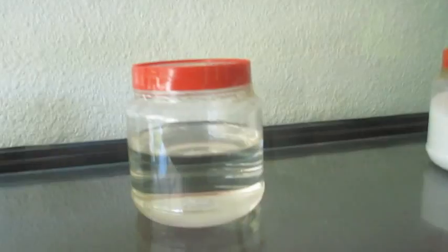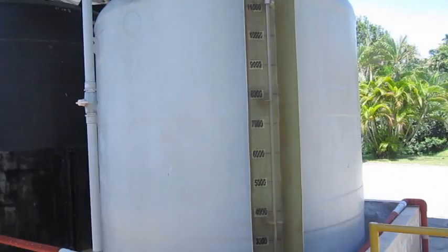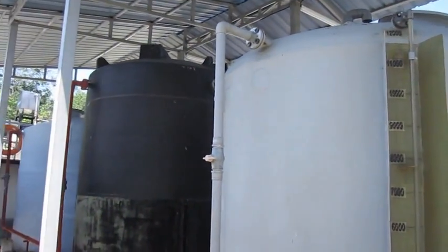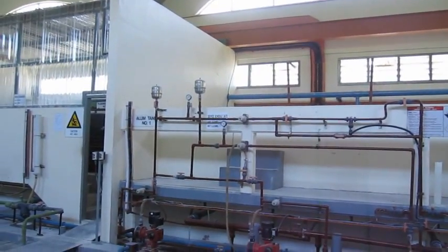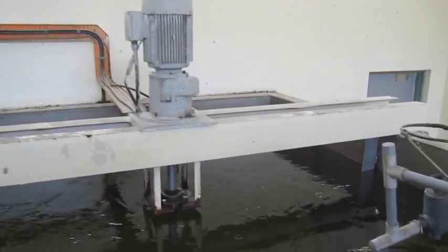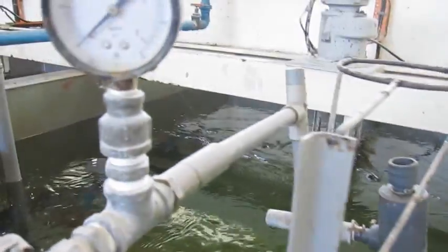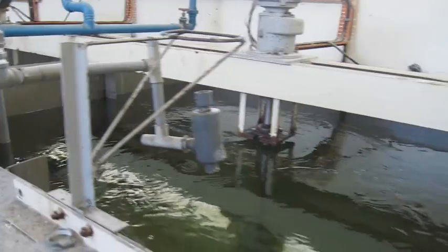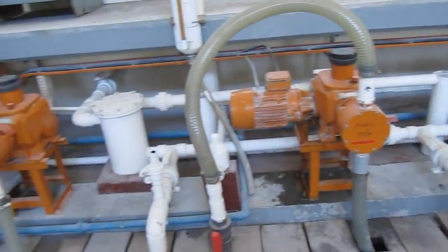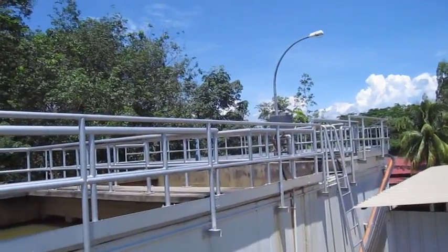Coagulants, usually alum, are added, leading to the formation of microscopic particles in water. This is followed by gentle agitation, causing small particles in the water to collide and combine to become bigger settlable flocs. All polymers used as flocculants in water treatment must be water-soluble, in water solution form. The active polymer in emulsion products is tightly coiled in droplets called micelles. These droplets are polymer emulsified in an oil phase.